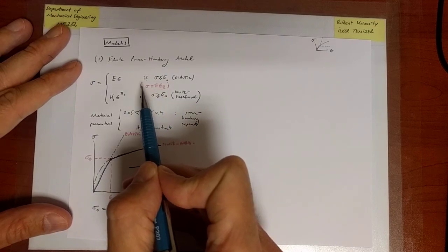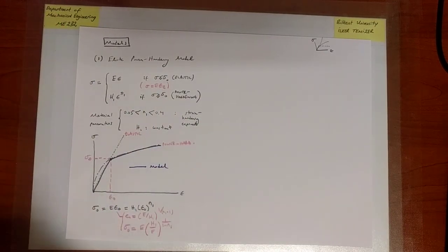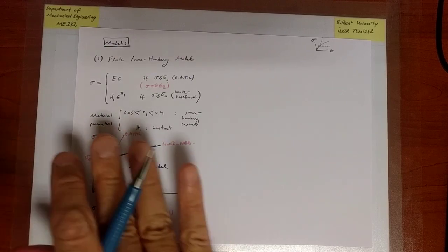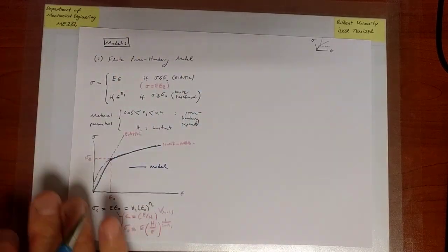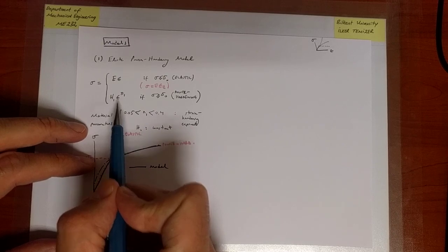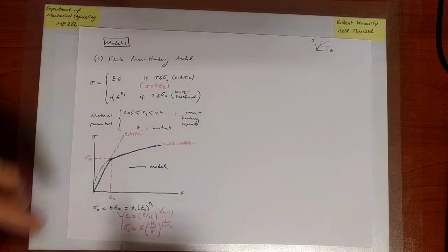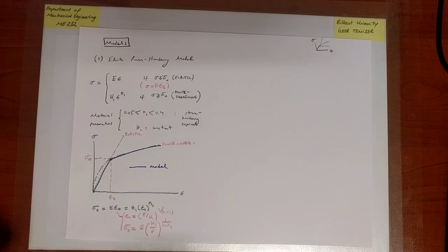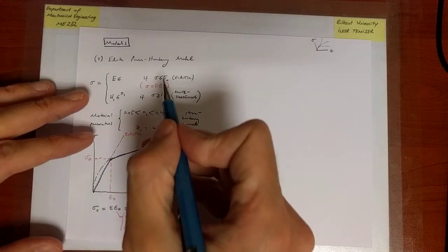You give me the value of strain to calculate the stress. I need to know what the plastic strain is. So notice that this model is taking a slightly different perspective. It predicts the value of the stress in the plastic region also through the overall strain. So that's the choice that the modeling is making.